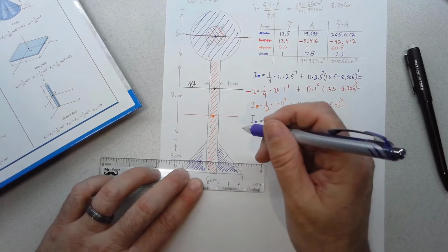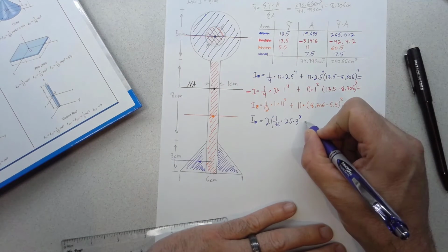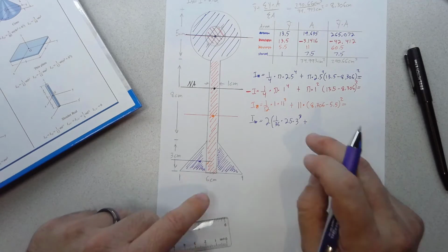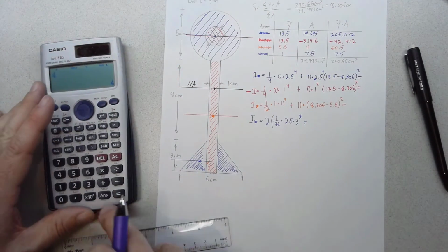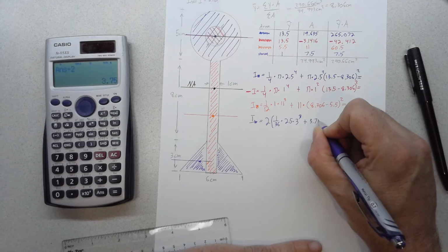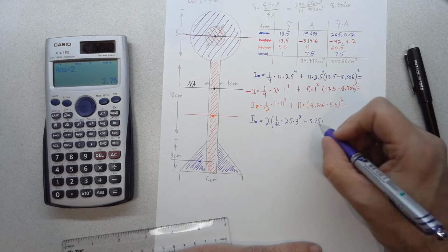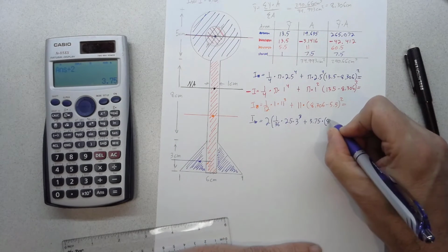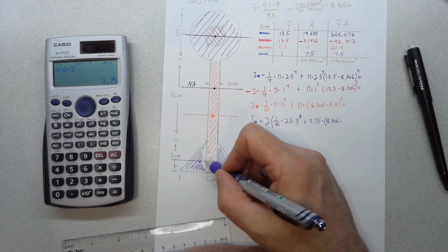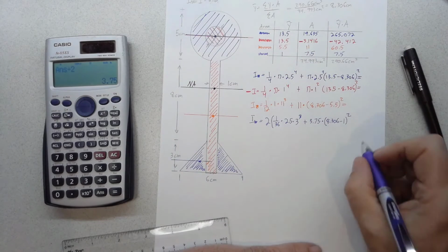that axis right there. But again, I care about it about the neutral axis, so I have to do the parallel axis theorem. So it's going to be equal to the area of one triangle, because I did the multiplying by 2 outside this, so I'm just looking at one triangle right now, which area of one triangle is 2.5 times 3 divided by 2, so its area is 3.75 centimeters squared, times the distance from this centroid to the neutral axis of the composite shape. So that distance is 8.306 minus this distance here was 1 centimeter, 1/3 of its height. It's 3 centimeters, so minus 1. And then that distance squared, right? It's always d squared.